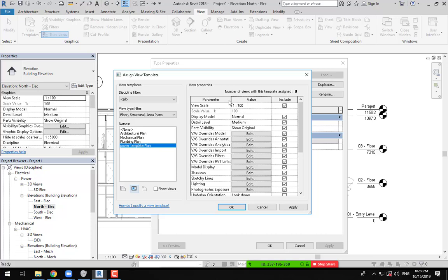Why do I need to save these options in the view properties to be activated through Power Template Plan? So I can use this Power Template Plan anytime in our project for level 1, level 2, level 3, level 4. I just need to select the Power Template Plan and click Activate, and all data and information that is already saved in this Power Template Plan will be activated.